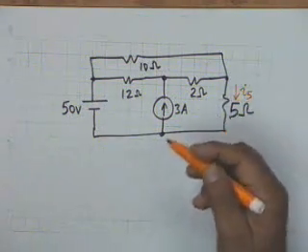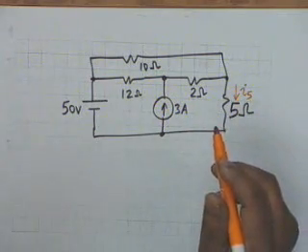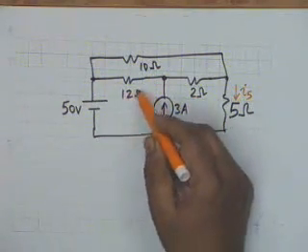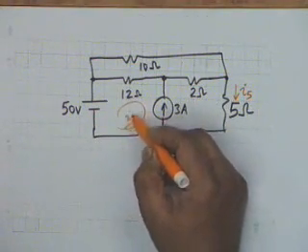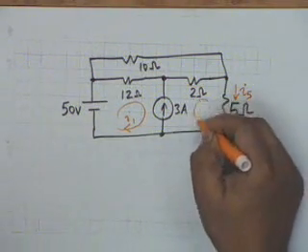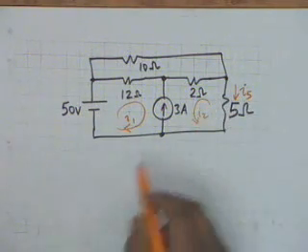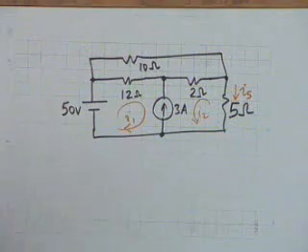For example, you can see that you can formulate 3 loop equations. Well, you could do that, except that, well, if you formulate a loop like this and a loop current, let us say I1, obviously, and a loop current here I2, alright. Obviously I1 plus I2 shall be equal to 3 ampere, minus 3 amperes, quite so.